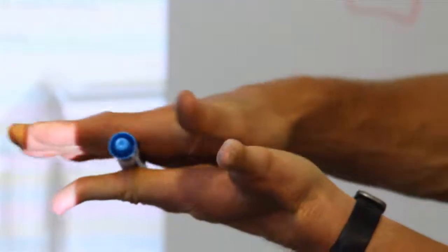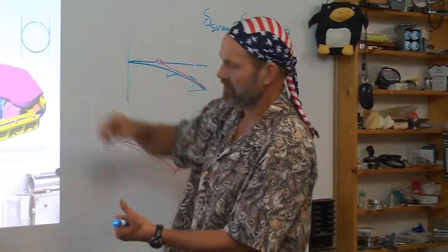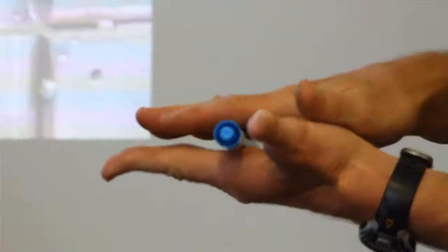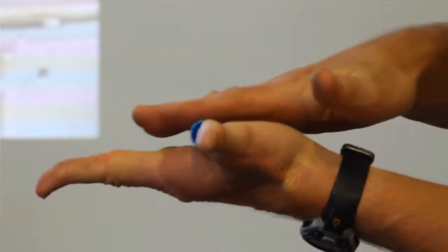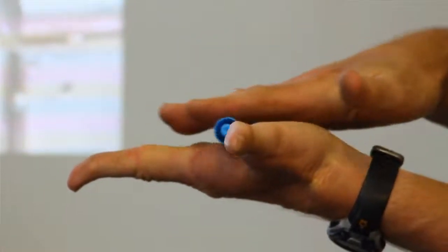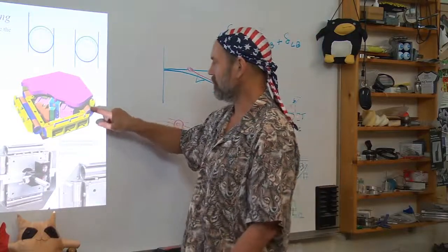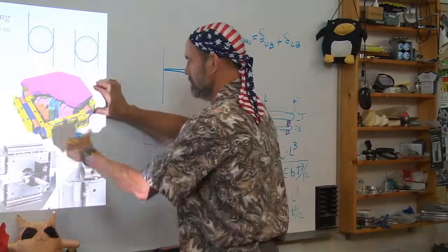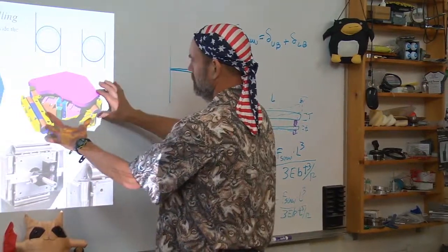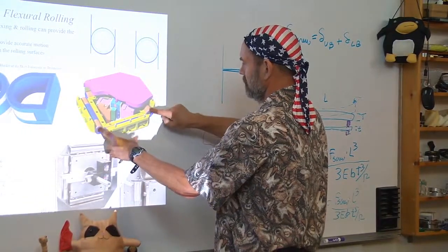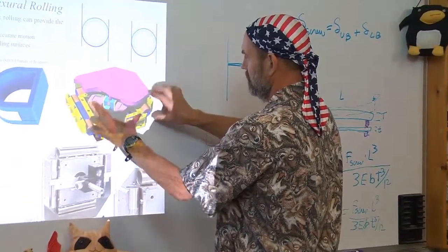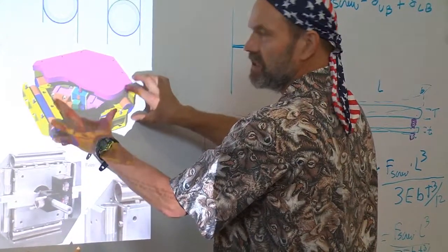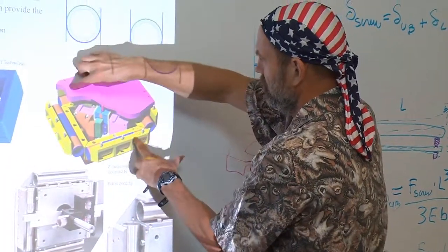And you end up with a structure with the bands on it that allows one to move with respect to the other, where the purpose of this intermediary roller with the bands is to cause, when this structure moves up and down with this rolling element band, it can't do that because the geometric constraint is that both sides of these rollers have to move up and down at the same velocity. And the same thing with the two on this side.